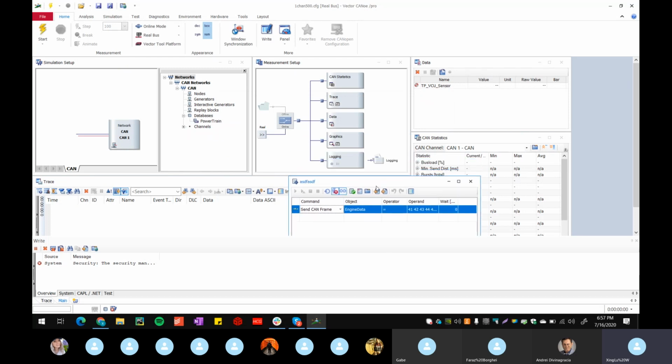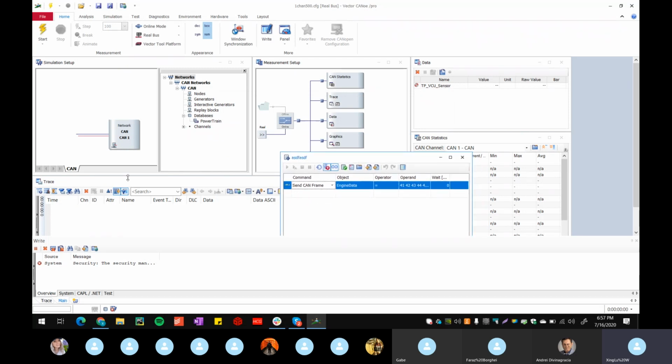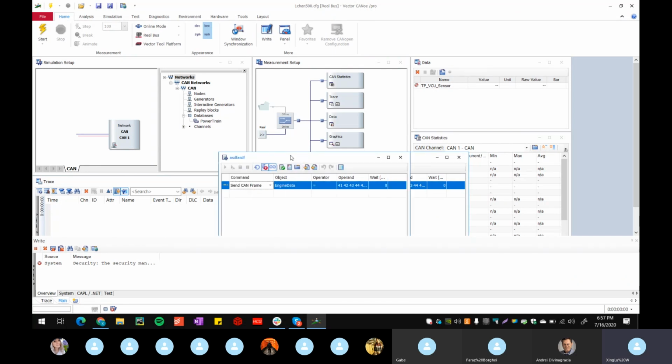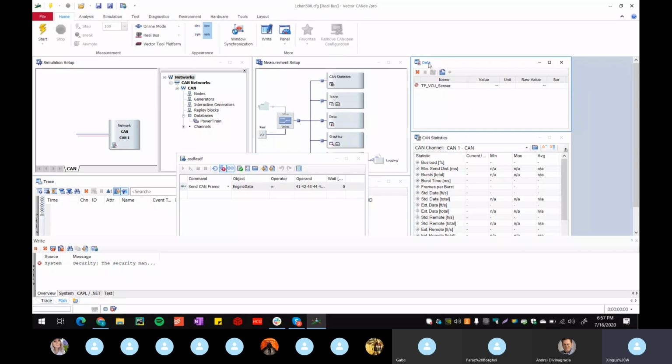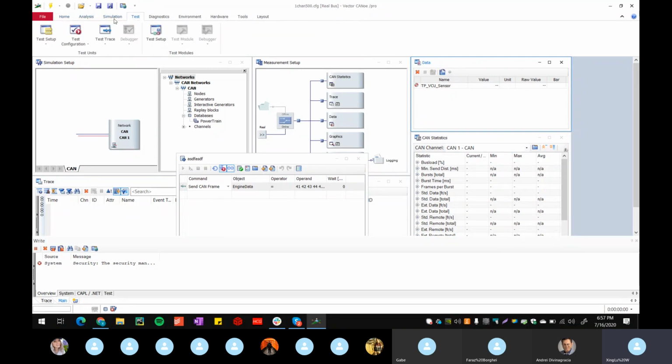So this is what I've been using to test CAN. In this part you'd see messages come up. Here is where the DBC integrates. Right now I just had something called Team Phantom VCU sensor, but if I sent the correct data, I could see values show up. It could refresh every half second or something. This tool is really powerful. It can do everything: analysis, simulation, test. It has its own built-in scope, which is pretty nice, especially if I didn't know if anything was actually turning on.